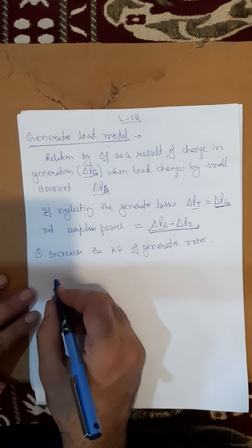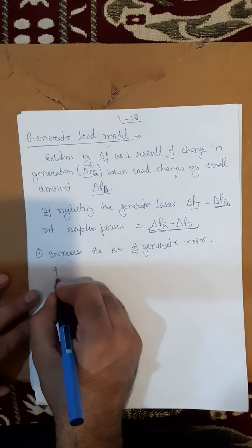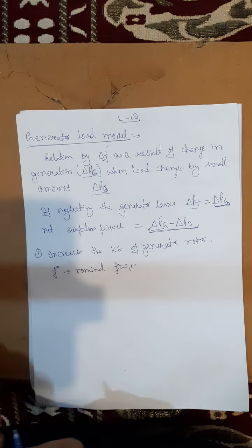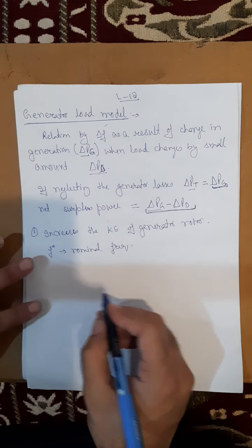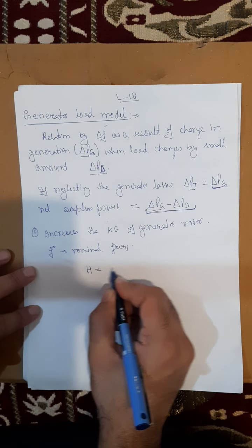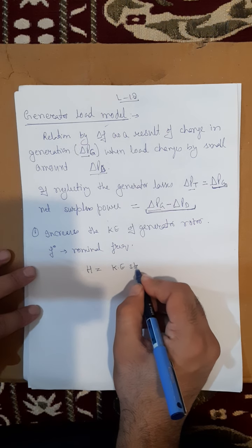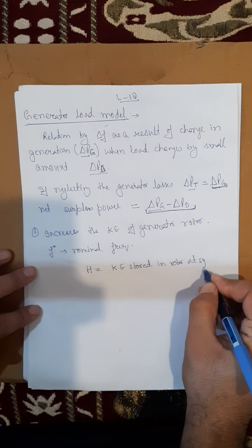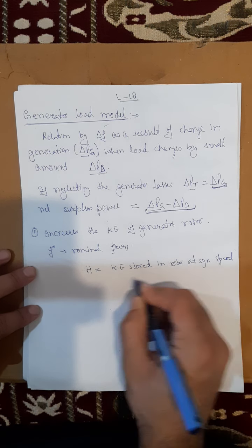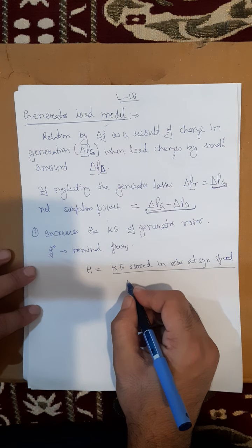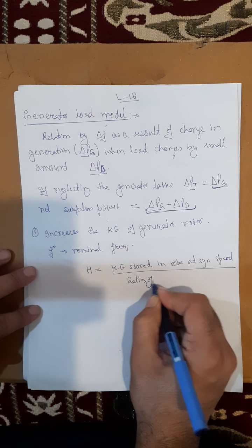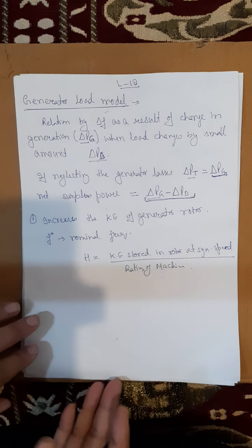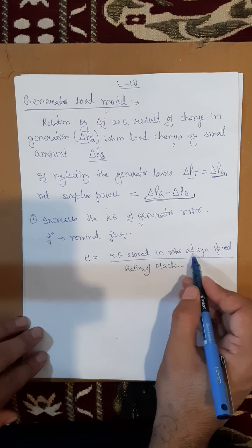At the nominal or scheduled frequency f naught, do you know what the inertia constant H is? It is the kinetic energy stored in the rotor at synchronous speed divided by the rating of the machine.